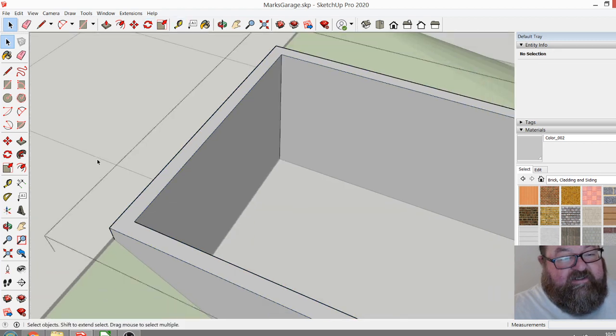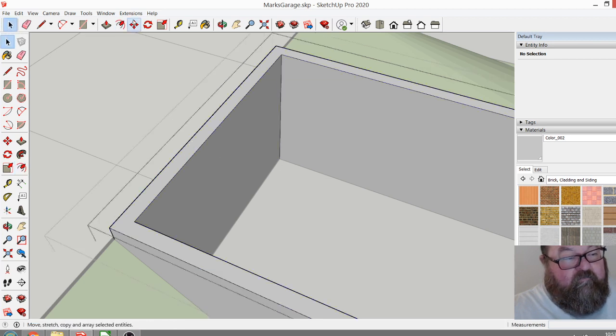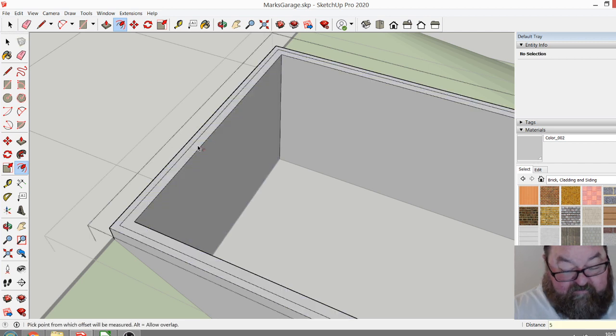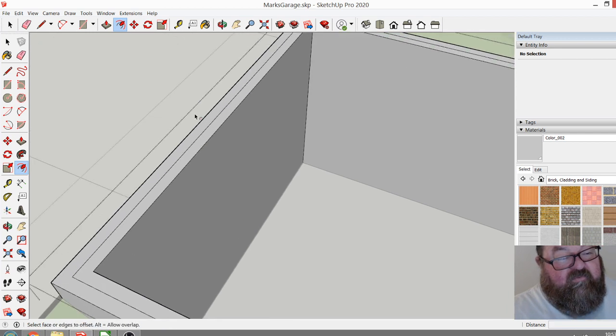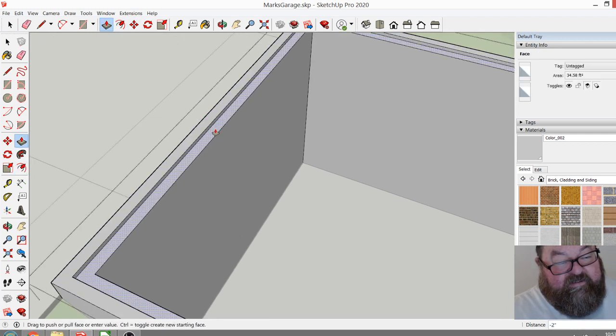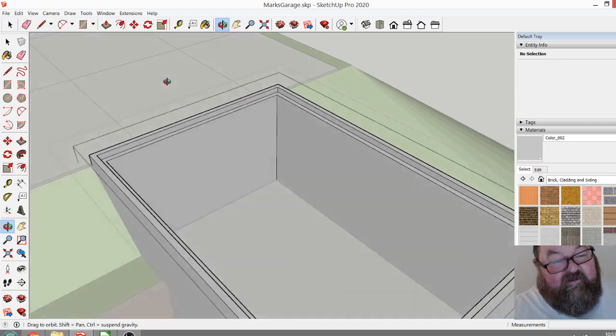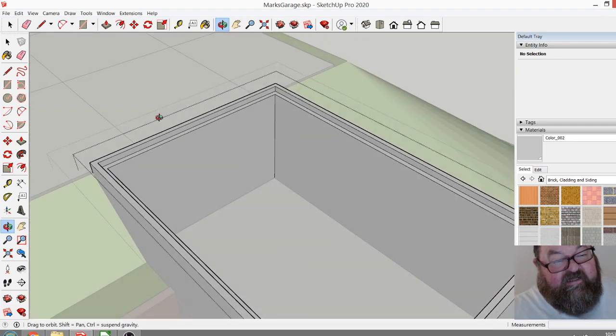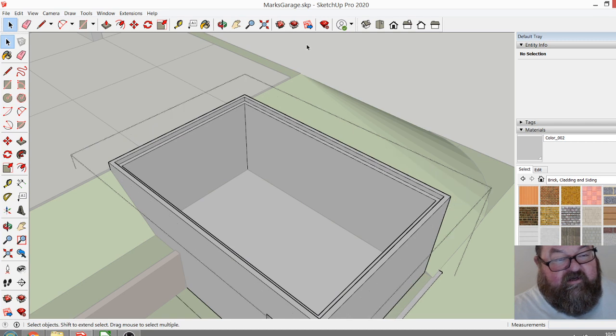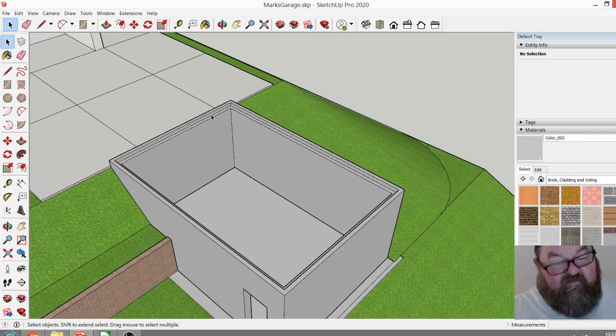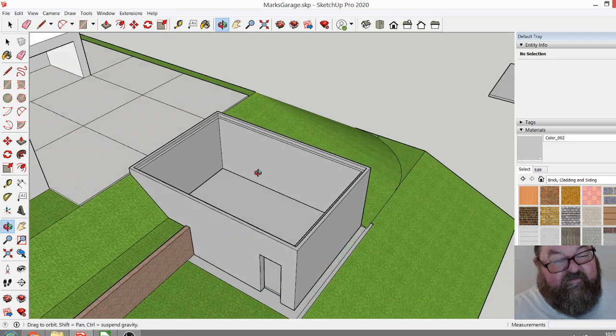So to do this, I'm going to come back half the width of my wall, 5 inches, and then I'm going to go down 6 inches like that, and that'll be our ledge. And this is not hard to do. The concrete wall companies are very familiar with doing it this way.